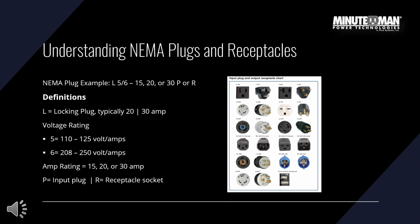NEMA plugs and receptacles. Have you ever looked at an electrical outlet or plug and wondered what those strange numbers mean, like NEMA 5-15R or L14-30P? Let's ask NEMA. NEMA stands for National Electrical Manufacturers Association. It's the body that sets standards for electrical equipment, including plugs and receptacles used throughout North America. Their goal is to ensure compatibility, safety, and consistency across manufacturers and industries, which is why you may have noticed the numbers on an outlet or a plug, to make sure the right plug fits the right power source safely and reliably.